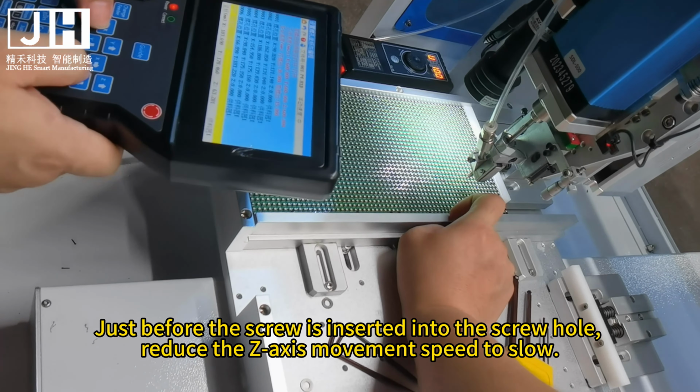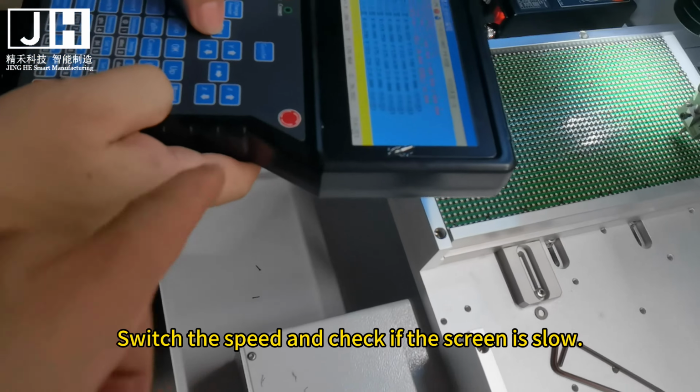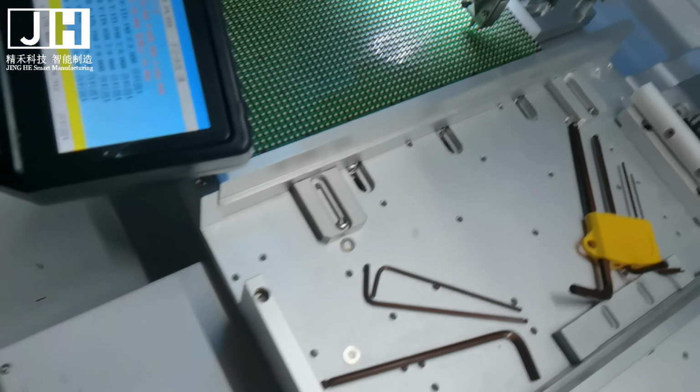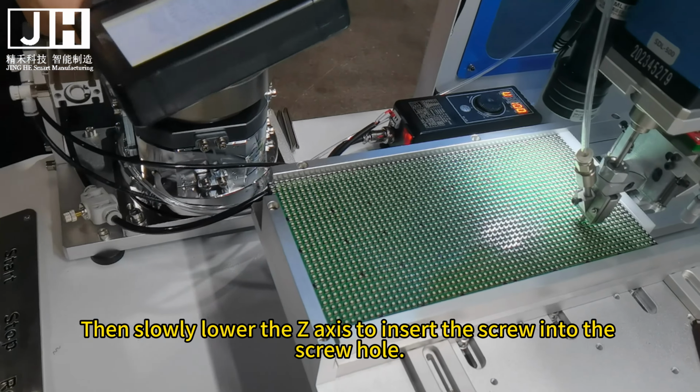Just before the screw is inserted into the screw hole, reduce the Z-axis movement speed to slow. Switch the speed and check if the screen shows slow. Then slowly lower the Z-axis to insert the screw into the screw hole.